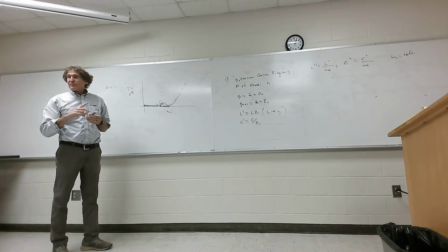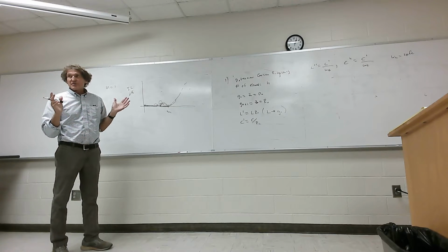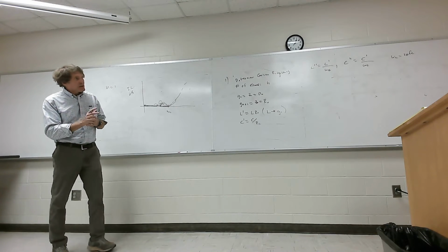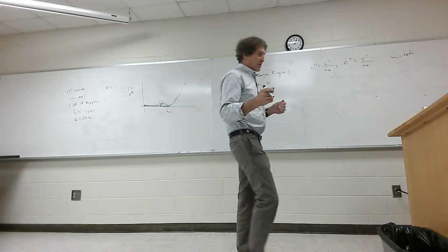And it really isn't that big of a deal, but there's never going to be a filter with more than 3 dB of ripple that would be allowed. Usually you want less than that, and he even has the good ones that are 0.1 dB. Then if you look in there, the next thing he wants.